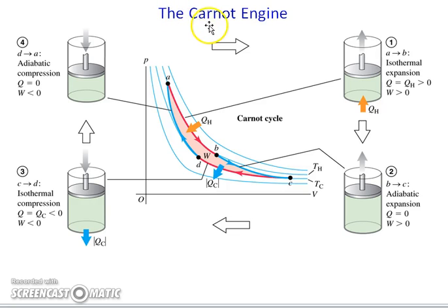What's the goal? As we saw earlier, the efficiency of a heat engine cannot be 100%, right? So the goal here is to find the maximum efficiency we can get. Our goal is to maximize the thermal efficiency. Here we'll talk about the idealized heat engine, and what I mean is, in an ideal engine all processes are reversible and no wasteful energy transfer occurs due to, say, friction. So it's an idealized case.